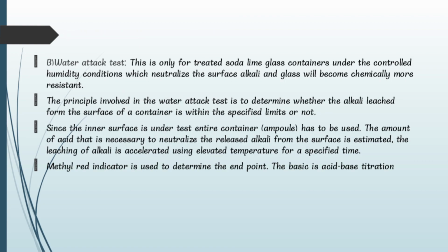Next test is the water attack test. This is only for treated soda-lime glass containers under controlled humidity conditions, which neutralize the surface alkali, and the glass will become chemically more resistant. The principle involved in the water attack test is to determine whether the alkali leached from the surface of a container is within the specified limits or not.